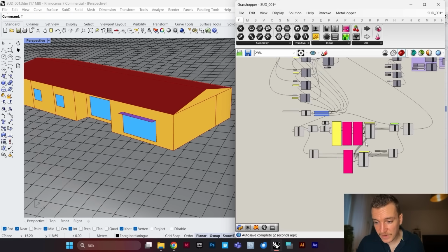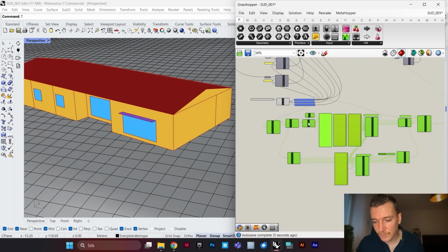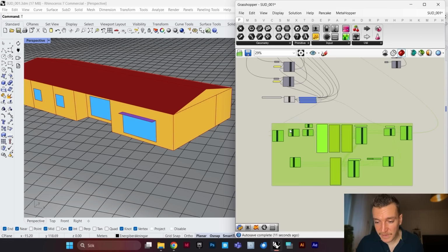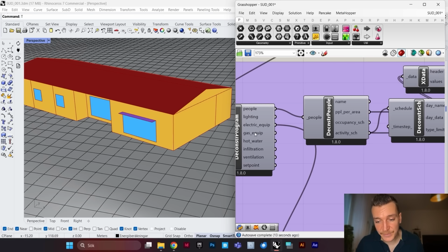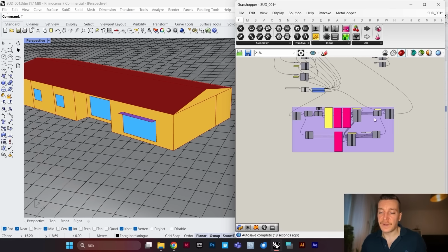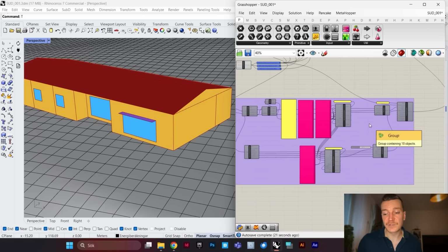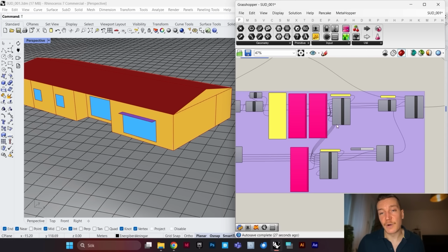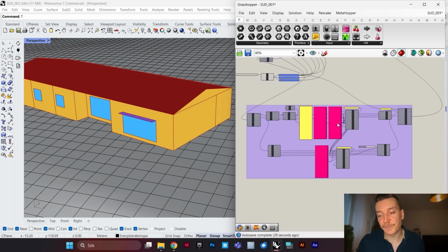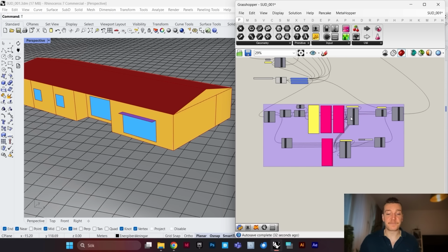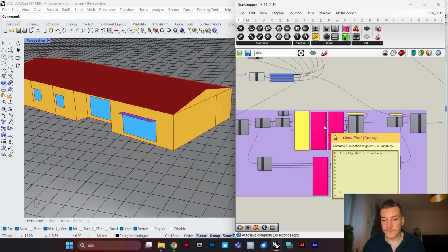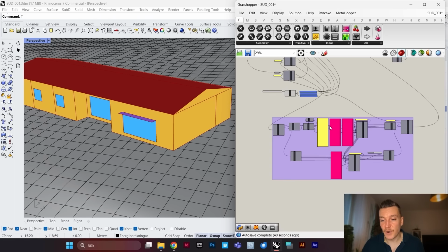And now we have created our own customized program for this room with our own schedules. And of course, if we want to make more changes, we can do so to the lighting, to the gas equipment, hot water, infiltration, ventilation, and set point. So whenever you're working with programs and loads, there's always this balance between accuracy and how time consuming it will be to create all these sets of data, basically. So for this example, I'm not going to make more changes to the programs.